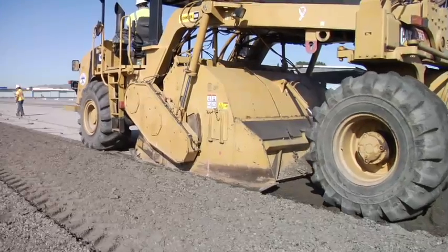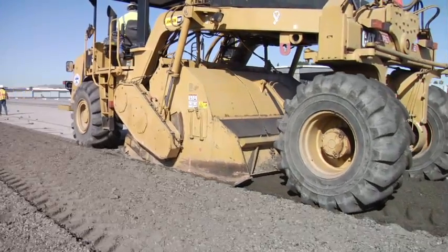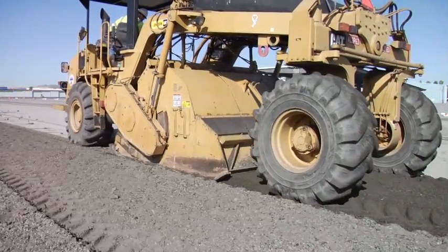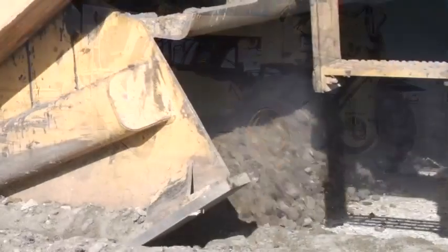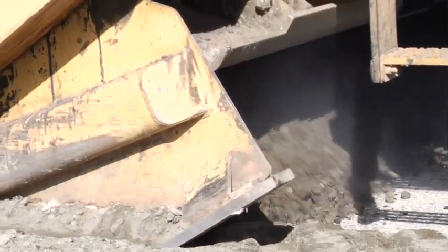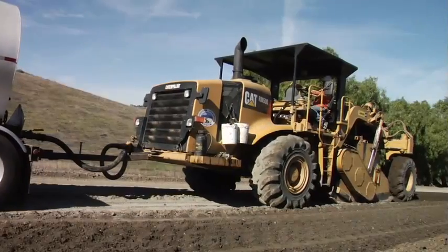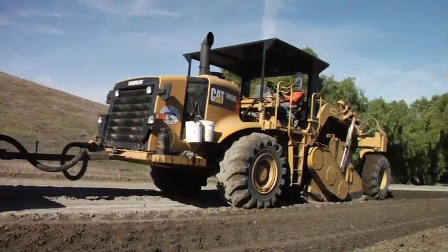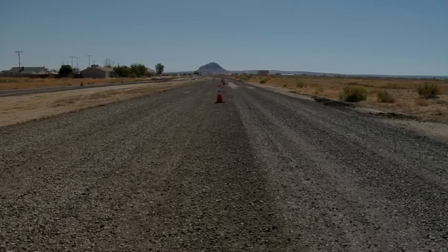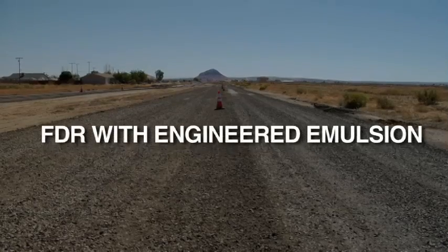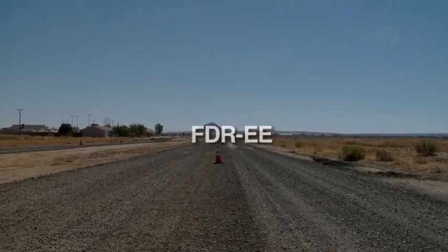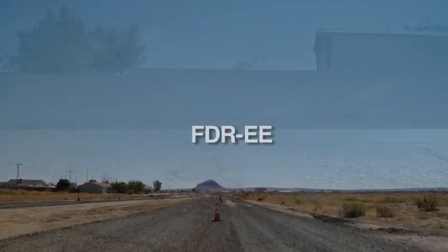Full-depth reclamation is the process of pulverizing an existing asphalt roadway and reclaiming the entire section into a homogeneous granular base. This blended material can then be upgraded with an engineered asphalt emulsion to make a stabilized base. This process is commonly referred to as FDR with engineered emulsion, also known as FDR-EE.